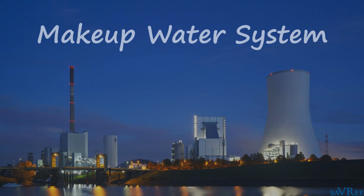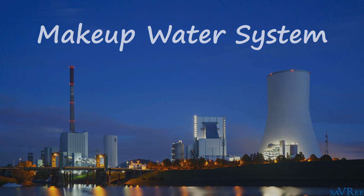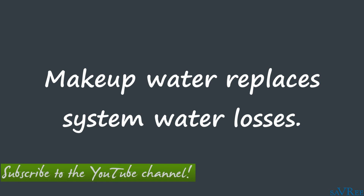Let's start by having a look at the makeup water system. Makeup water is sourced externally from the power plant. It is water that you add to the condensate or boiler feed water system in order to make up for any water losses that may have occurred in the system.